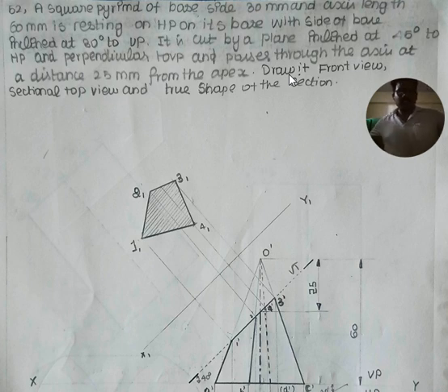Here the given object is a square pyramid, and it is subjected to sectioning. After sectioning, we have to draw the front and top views. That is the question we have got. So square pyramid means it has one base and one apex. The shape of the base is a square. So four base sides, four slanting edges, one apex, four base corners. These are the four triangular faces. These are all the main parameters in a square pyramid.